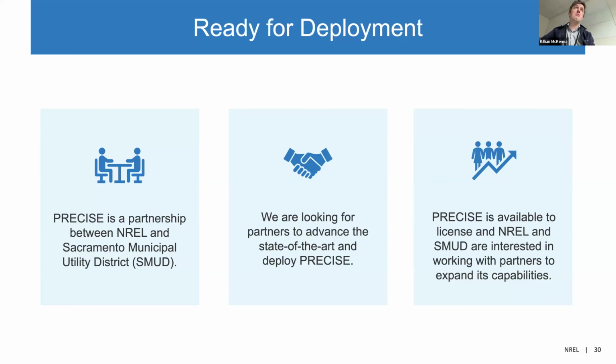And really how Precise differs from those screens is that we are actually doing the power flow analysis, impact analysis, instead of using heuristic screens that compare the nameplate of DER to the nameplate of transformers or the feeder peak demand. There's a number of different percentages that they have for recommended limits. And those recommendations are really based on not having the visibility of the actual impacts.